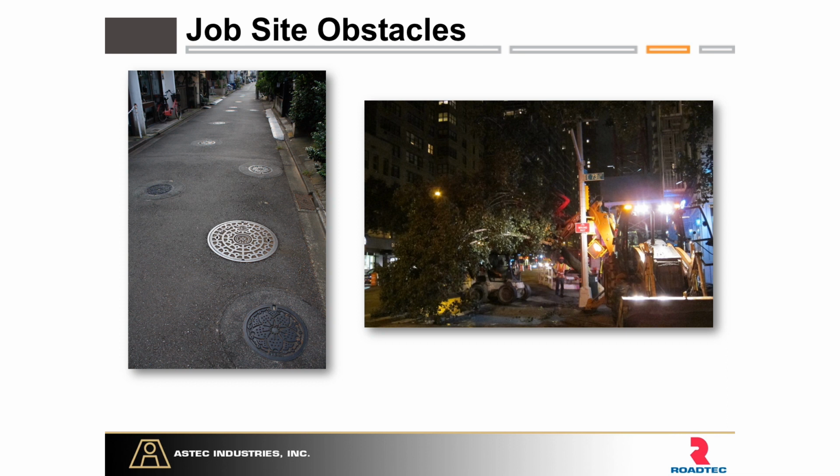On the right, you see a tree here that was ripped out by a milling machine, and that should have been a part of the game plan. We should have accounted for these low-hanging trees. Perhaps we could ask for another lane closure, temporary, until we get through these trees. We could offset our dump truck, move our conveyor, try to minimize the damage.